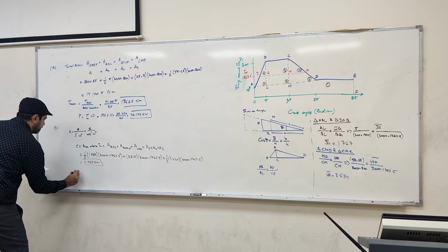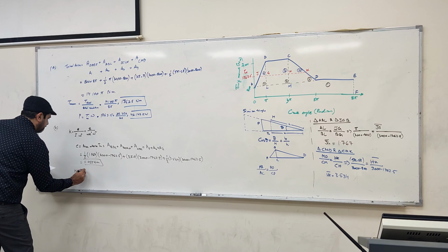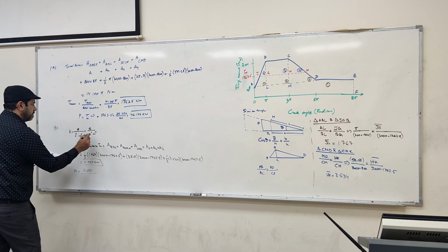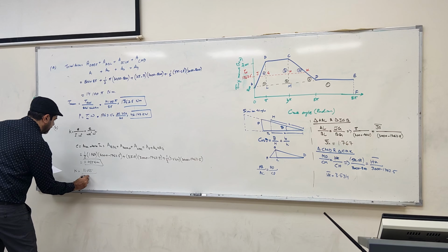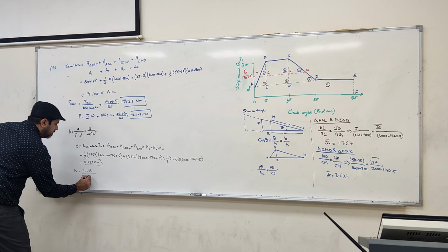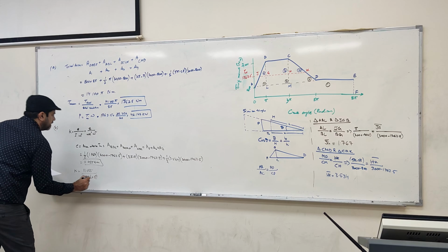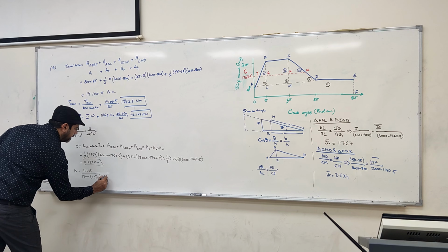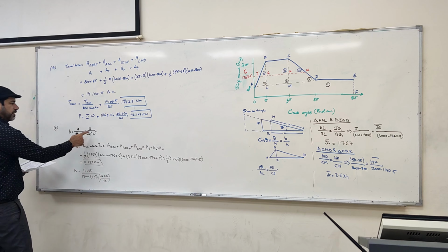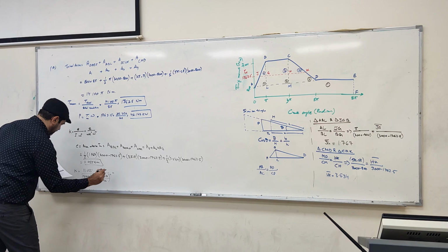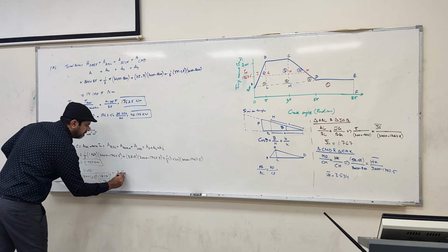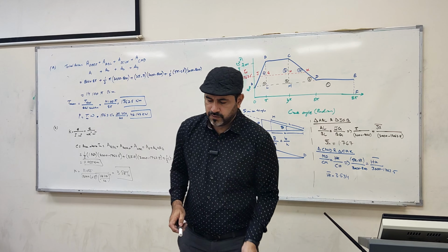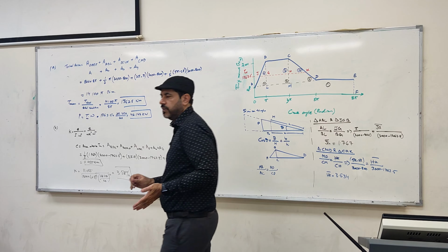And then you put it into the fluctuation: 11055 divided by, what is the form? M, which is 800. Radius of gyration is 0.5. Omega is in RPM, so we need to convert it to pi n over 60. Don't forget this square. Once you put everything in, you turn out to be 3.58% fluctuation observed for this task and this flywheel.